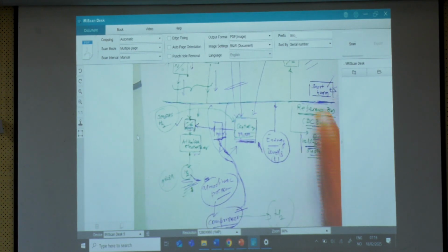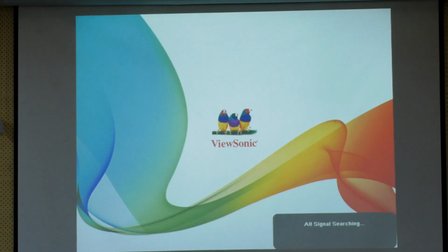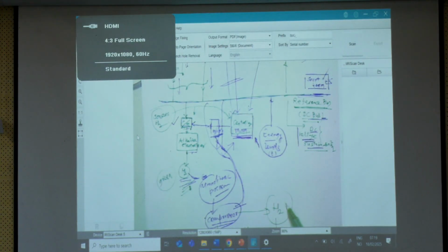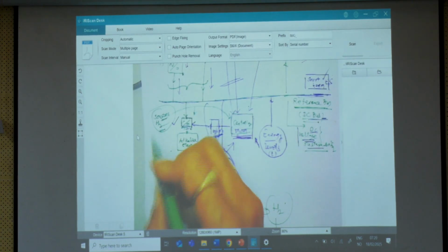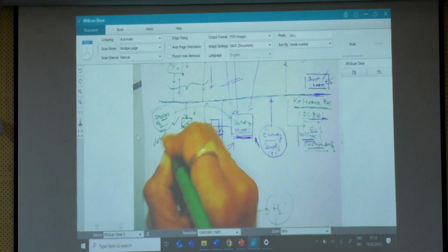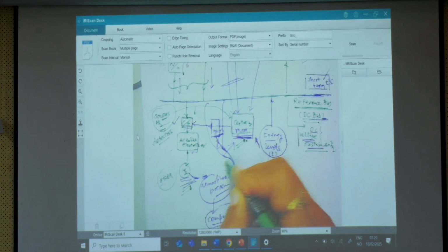And if suppose there is any leakage of the hydrogen at any level, whether at the alkaline electrolyzer production level, maybe at the compressor level, or maybe at the storing level, all that information through these hydrogen detector sensors needs to be integrated in this controller for making the decision for stopping the operation of the system completely.